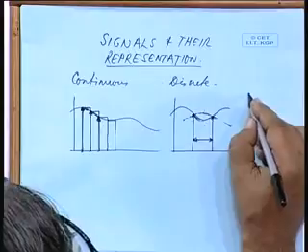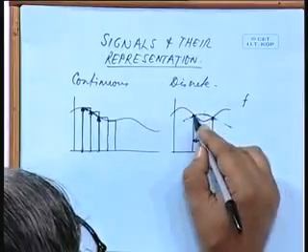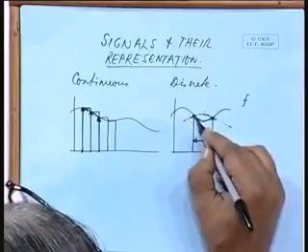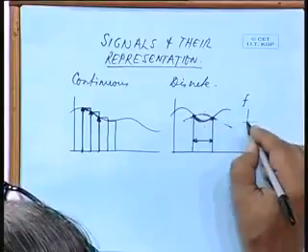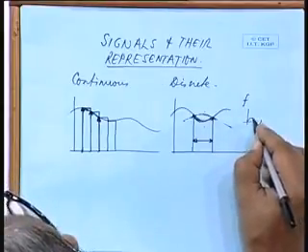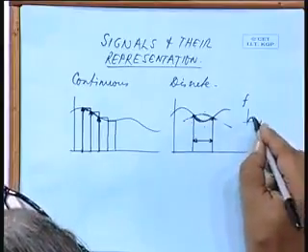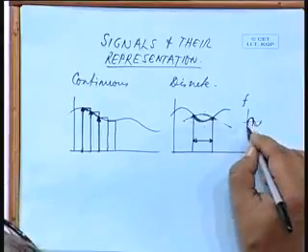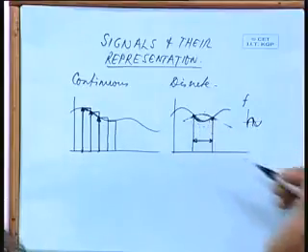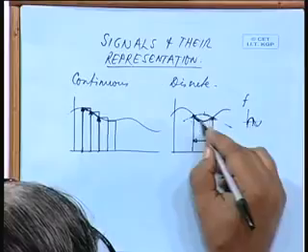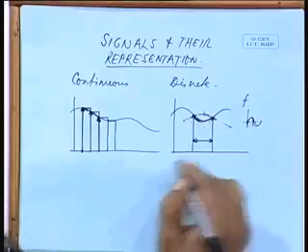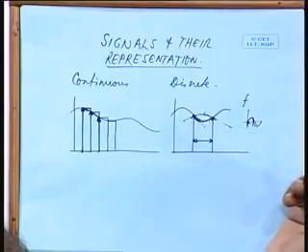is represented by some frequency, this represents half that variation. Suppose this can form at the most half of a cycle, half of a sinusoidal function. Okay. This is a maximum possible change, and if I take half that value, then I will be missing out the trough or the peak. So, the sampling frequency should be such that I do not miss out this. So, half the length means twice that frequency that is present.